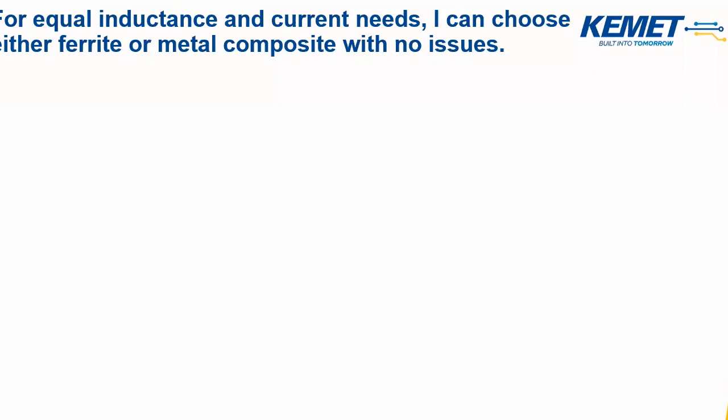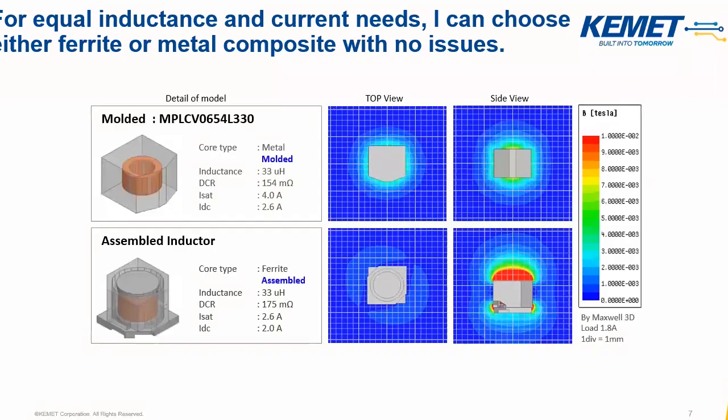In an ideal world, maybe, but we are not living in an ideal world. So actually, this is like if you want to change from electrolytic capacitor to film or MLCC without thinking about their different behavior. And it's unfortunately much more complicated because you have to consider much more than just the inductance and the current of the used inductor. There's much more, like the RDC or the impedance.